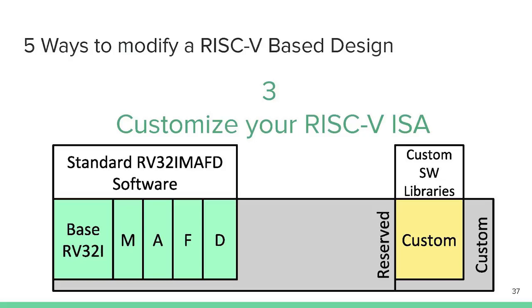Similar with F, which stands for floating point, which is a pretty expensive piece of hardware in any case. And if you're just a power CPU controller thing, I've never designed one of these, but you probably definitely don't need floating point. So you're not going to waste area for that. And similar with the A and D and other extensions. So the idea is the hardware is modular, and therefore the compilers know that, and the compilers are modular.